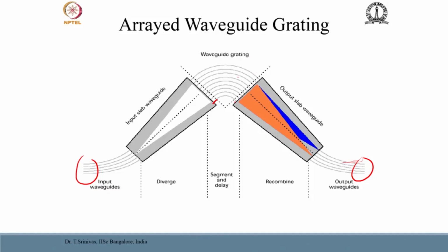designed, the lengths could be designed such that the phase shifts across each of these when combined at the output port could lead to superposition only at one port for a given wavelength. So, it is possible to focus each of these wavelengths that are coming from the input port at different output ports using such a structure.